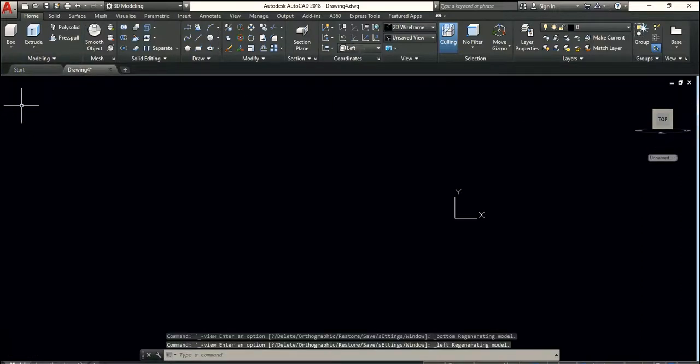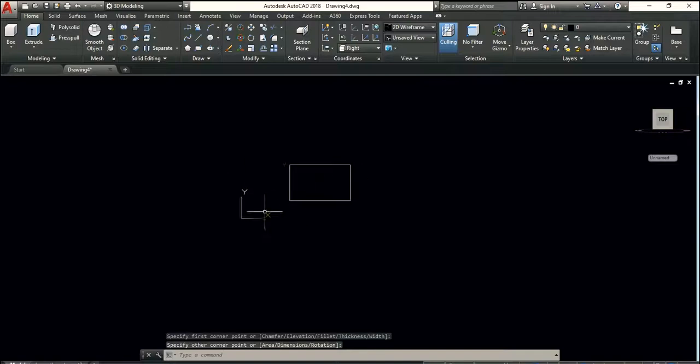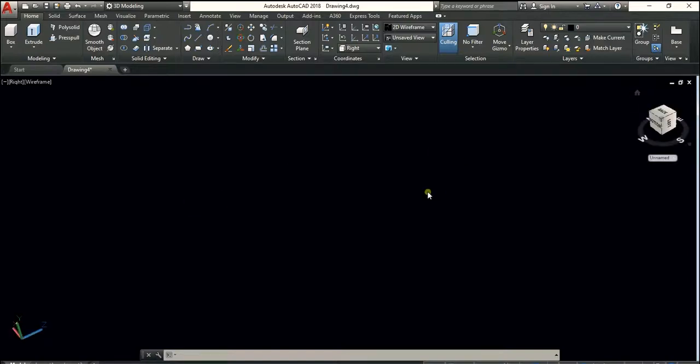You can also flip your left, your right, and also don't mind this name, this is just the viewport, but the coordinates is switching itself. So when you are creating anything, this is what you should notice, not this. Because right now if I have my right view, that means I can create my object in my right view. That is what it means. So I can create this rectangle in my right view. Then if I go to the isometric plane, you will see what I have.